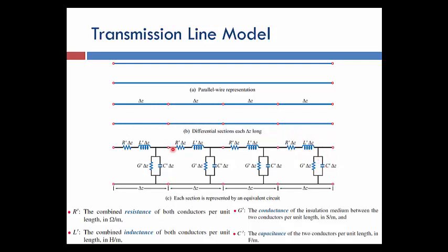In real there is, of course, no reactance part, but there are their effects. These two wires work as inductor and capacitor. So again, the applied signal will be attenuated by R, and delayed because of the existence of L and C. It could also be reflected because of the effect of L and C. Some of this signal, or maybe all of it, will propagate in the opposite direction, and that's what we call reflection.